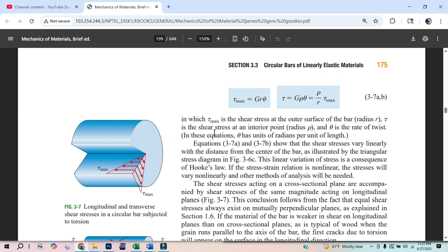And so if you have a long shaft, even 1,000 millimeters, even if it's just a meter long shaft, because of the small angle approximation, and you don't have to use small angle. You could actually just, but you have this angle of 0.004. And you have a length of the shaft of 1,000. Which small angle just says, hey, that's going to be equal to the hypotenuse, the length of the shaft, and when it rotates, the hypotenuse is going to be the same length anyway. So you have a hypotenuse of 1,000 and an angle of 0.004. So that distance, the arc length that it actually rotates, is 4 millimeters. So cool.